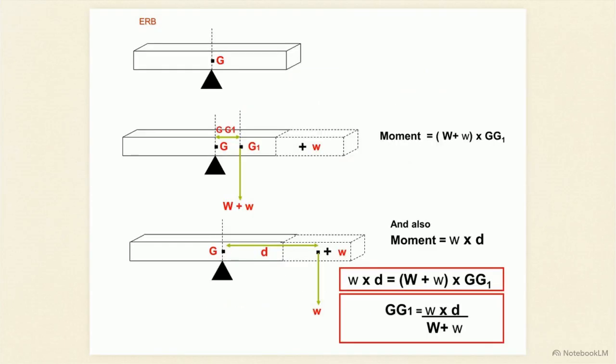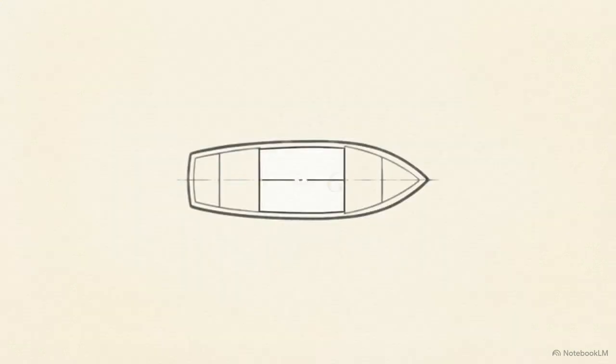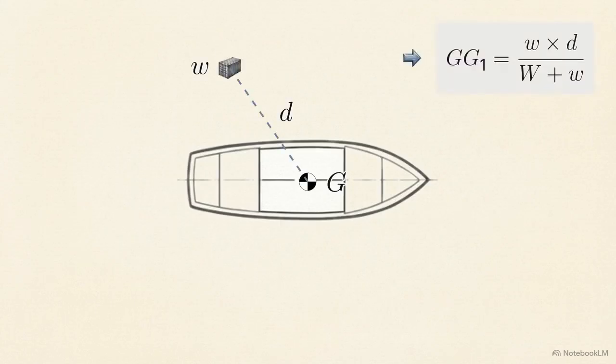Conversely, these sequences demonstrate what happens when mass is added. Adding weight pulls the center of gravity toward the new mass. The math in the round box remains identical, but we add the new mass into the denominator, calculating total weight as W plus w. Any individual weight change causes a calculable shift in the overall center of gravity. By knowing the exact weight, its distance from the center, and the total mass of the object, you can predict exactly where the new balance point will be.